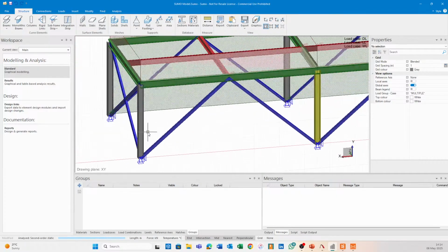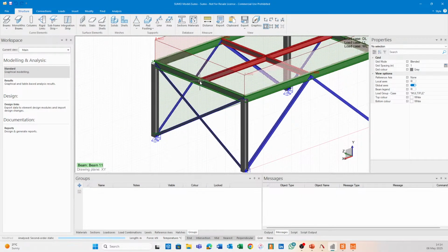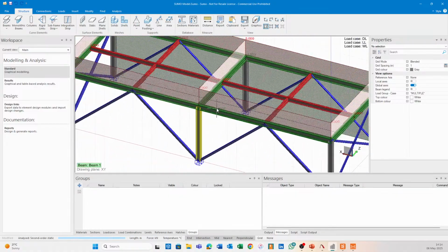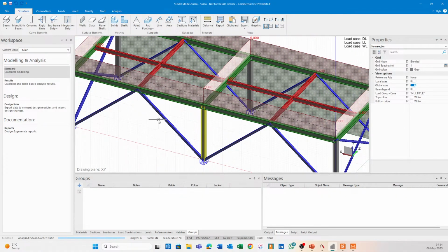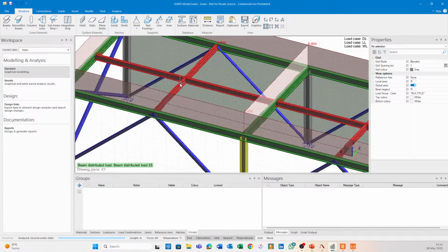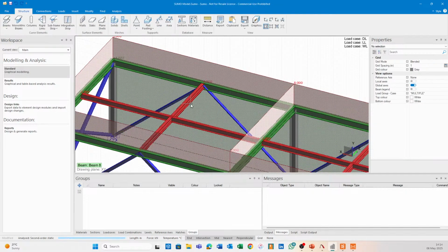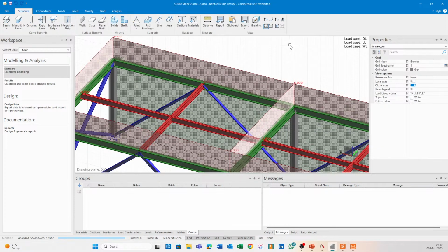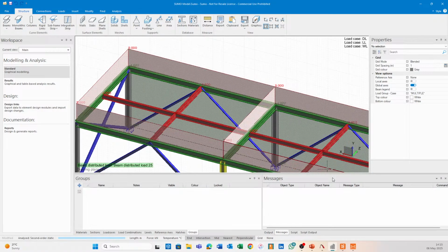All right, so it's very important that, if you want to make use of the design link, you pay attention to the orientation of your members. So say, for instance, if you want this member to be horizontal, so basically with the web being horizontal in IDEA StatiCa, through the use of the design link, you actually have to rotate it within your Sumo model and then proceed with the process. Okay, once you've pulled this through into Checkbot, it is pretty much locked in.